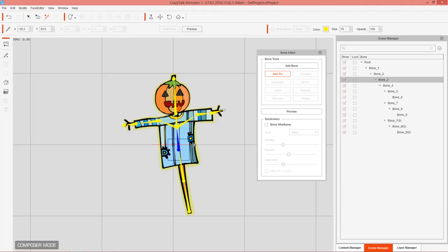I'm going to click down here and add a few pins. I'm going to click on our mesh right here on all four sides, and then I'll right-click to stop adding pins, and then you can click and drag pins to move them around later on as well. But all these pins are now connected to this center. You can see the hierarchy right there: pin, group, bone.